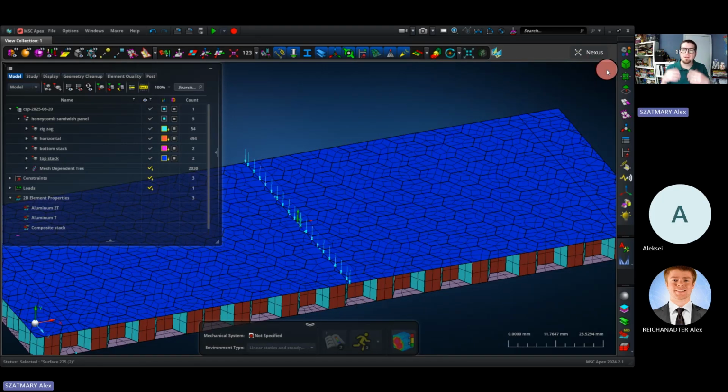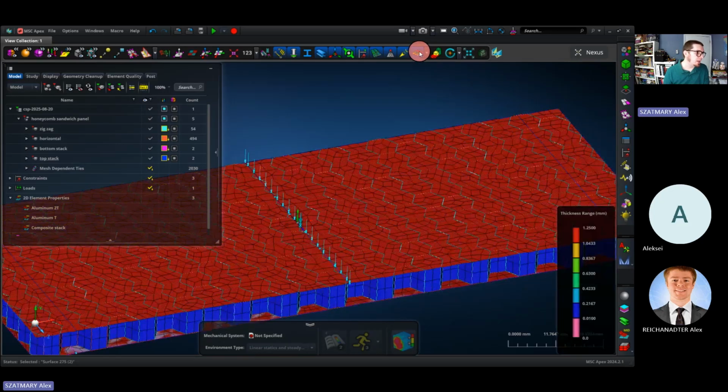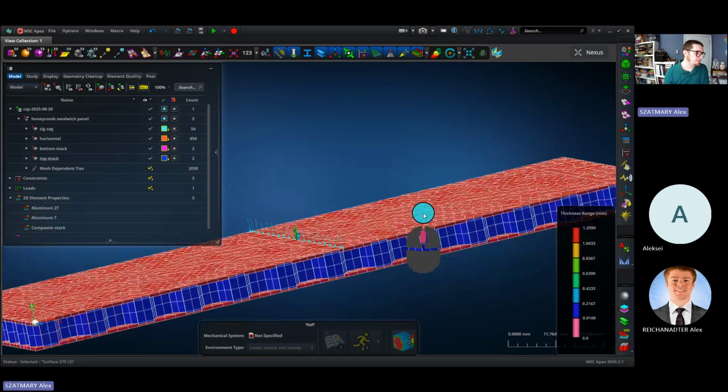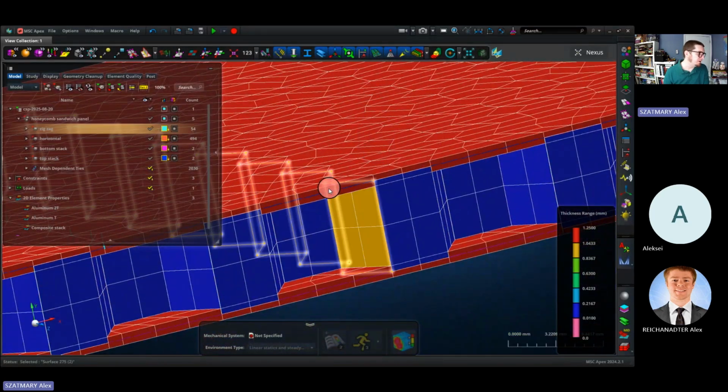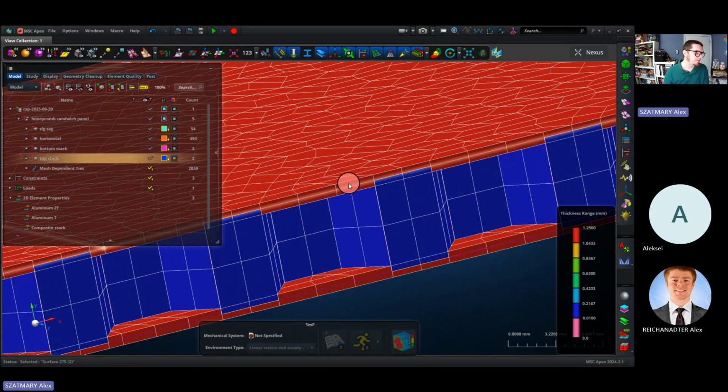Let me show you some work for manipulating the element directions and positioning. So we can preview how Nastran would think about these shell elements and their thicknesses with this shell thickness button, which by default just color codes based on thickness, but we can actually visualize the thickness here. So we only have surfaces and shell elements in this model, which are infinitesimally thin, right? They're flat, but now we see them rendered with thickness corresponding to the properties that we assigned.